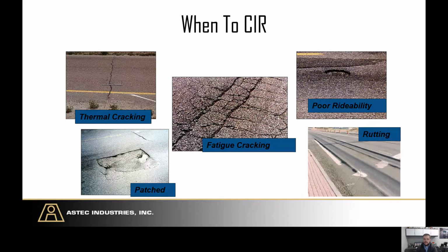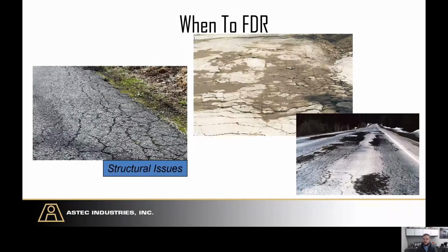So when to CIR? Cracking is a big one. Some patching, rutting, geometric issues, if they're not too deep, we can correct those. And then full depth is when your base is failing. If you have a road that's carrying more traffic than it was ever designed for, that's when full depth reclamation really shines.